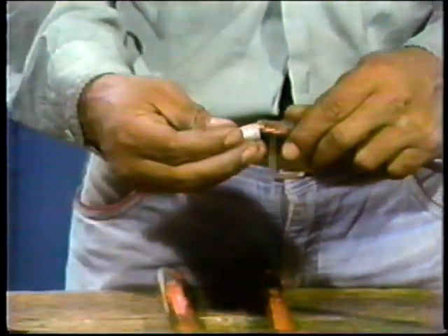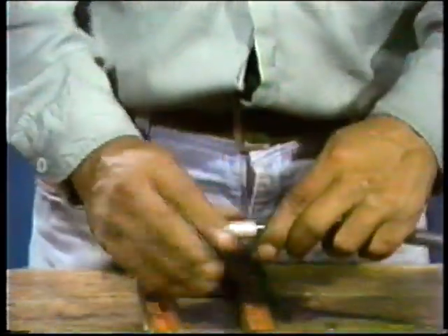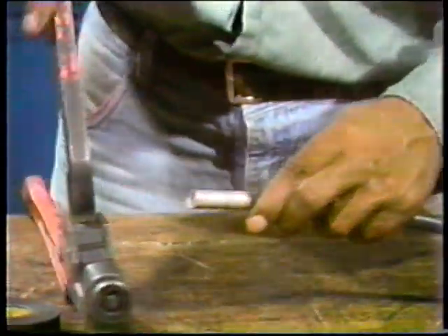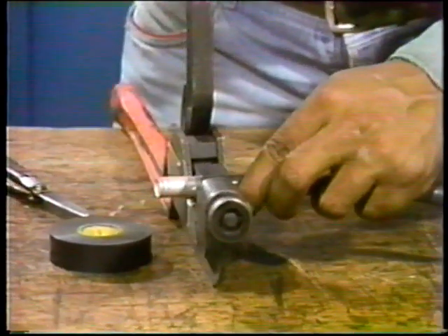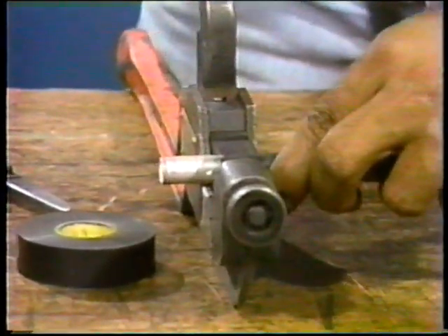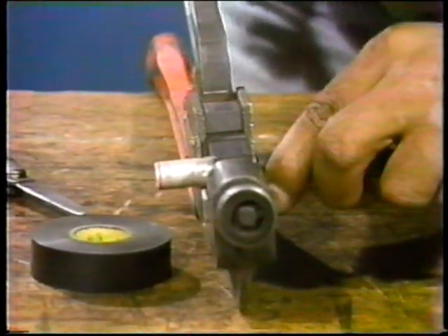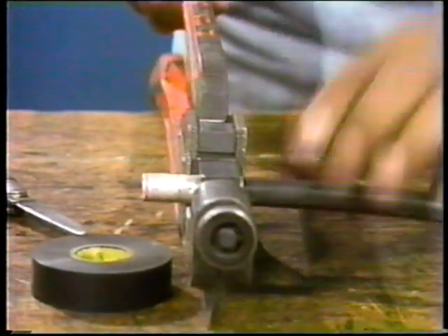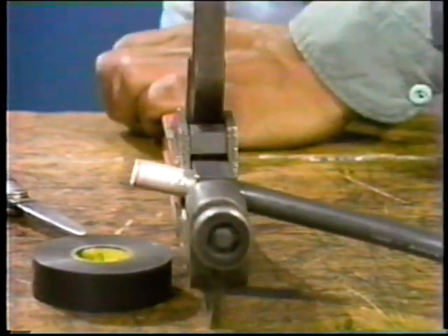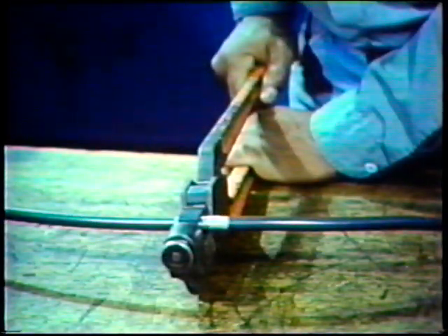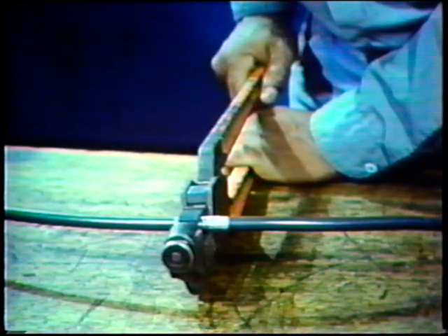Bill inserts the end of the conductor into one end of the sleeve. Then he places the sleeve into the jaw of the crimper. He makes sure the end of the sleeve is centered so the crimp will be just where he wants it. Then he squeezes the handles of the crimper together until they reach the stop point. Now he fastens the other end of the sleeve to the other conductor the same way.